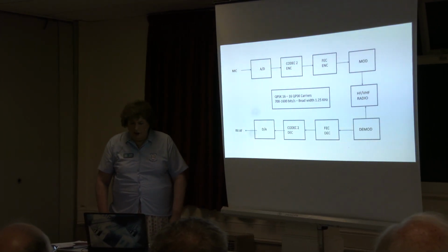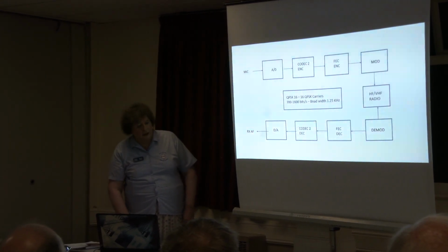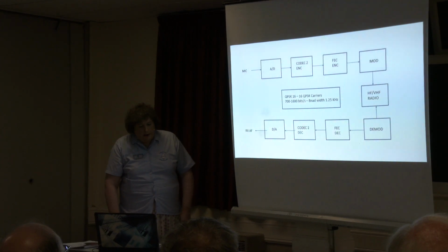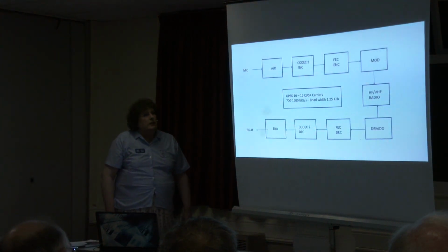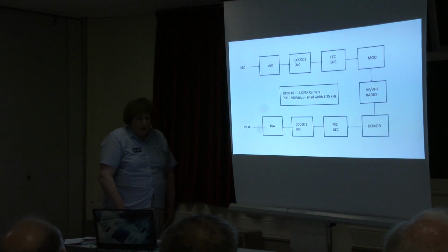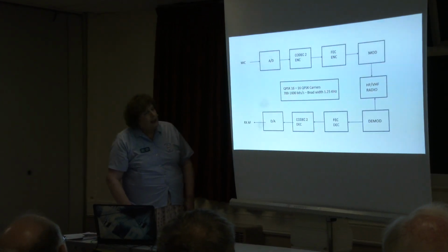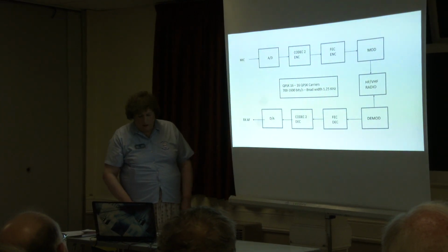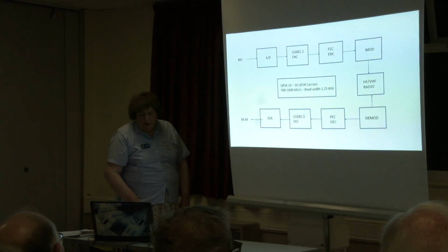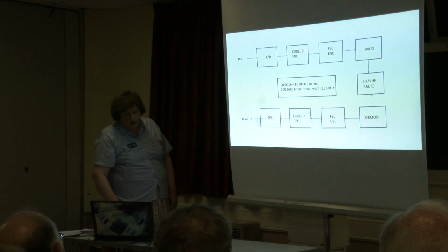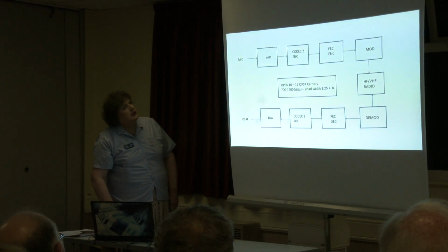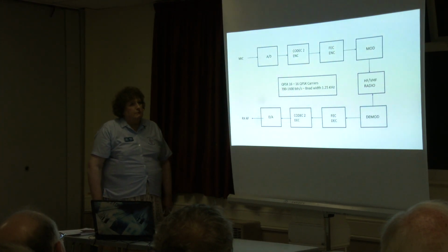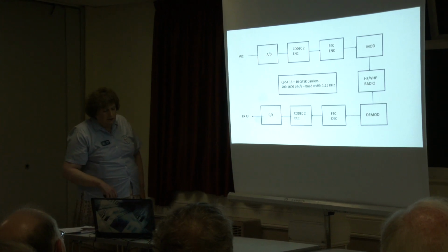So that's a good space saving as far as spectrum is concerned. On the 1600 bits per second setting, we have 25 bits of text for your call sign ID, 300 bits for forward error correction, 16 times 50 baud QPSK carriers, and differential QPSK demodulation as well.